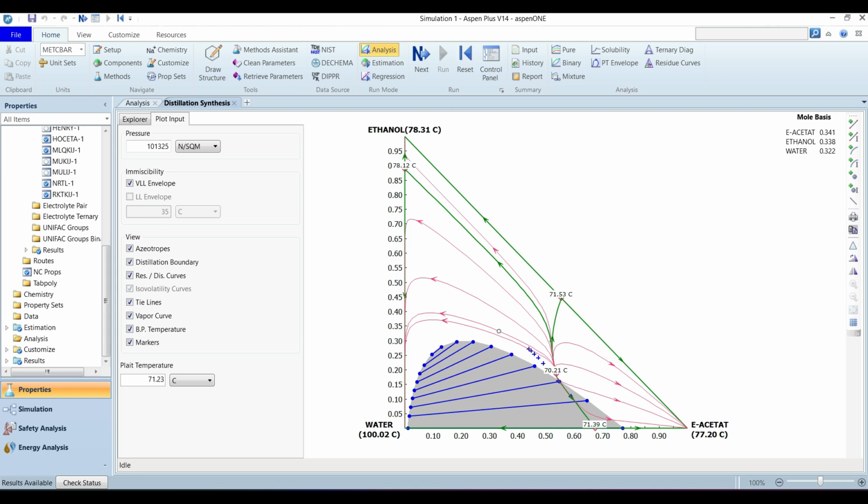There are the arrow options over the residue curve. So following the arrow, the same feed goes to the right option, and that right option landed very close to the pure water ultimately. And if you follow back, that lands up at a 70.2 degrees Celsius azeotrope. So that azeotrope should be in the reboiler or in the condenser? In the condenser. That is 70.2 degrees Celsius.